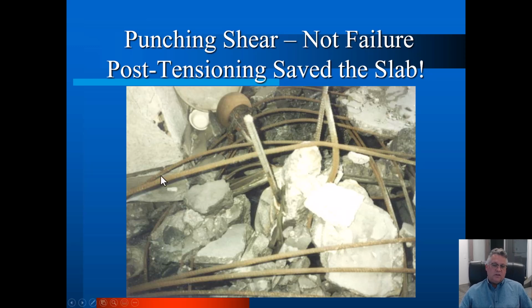But in this case, it looks like somebody came along during the earthquake and cleaned all the concrete off the rebar. The concrete just shatters off of this rebar. So any of these details that rely on bond of rebar to concrete, in my opinion, are going to be useless for this integrity type of reinforcement.